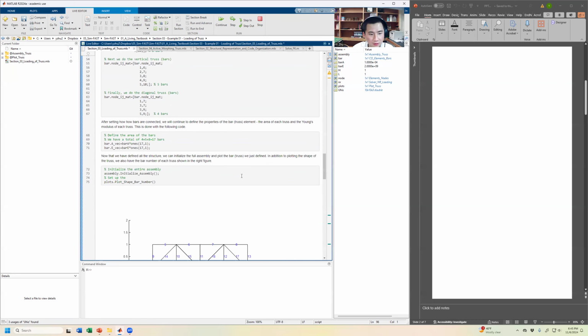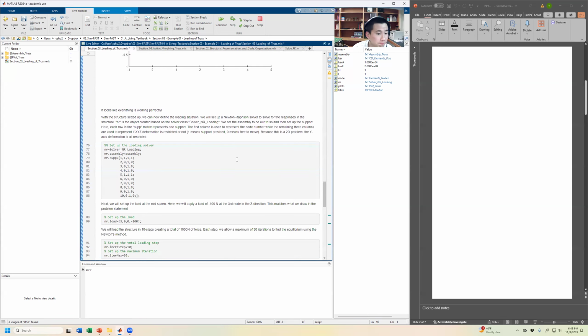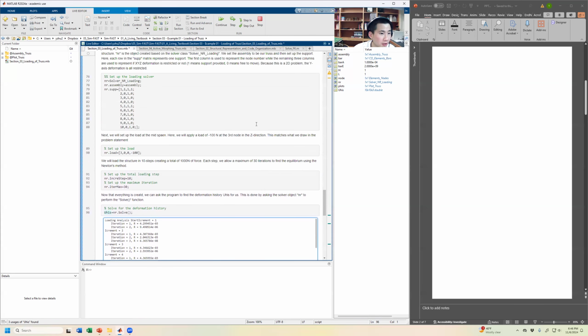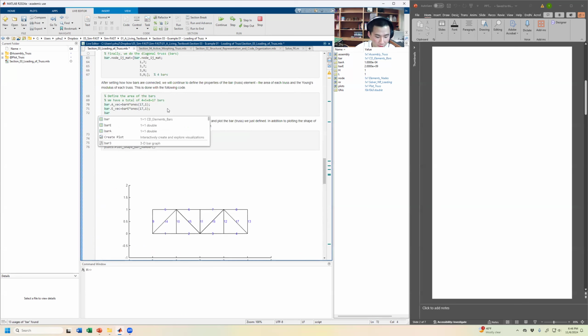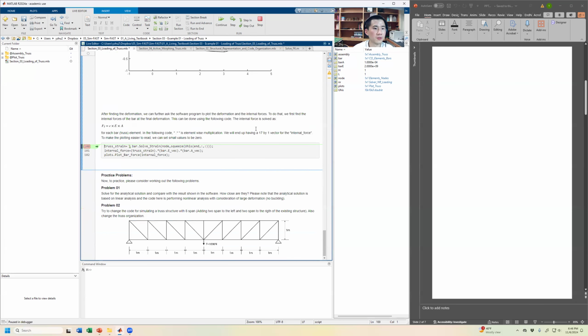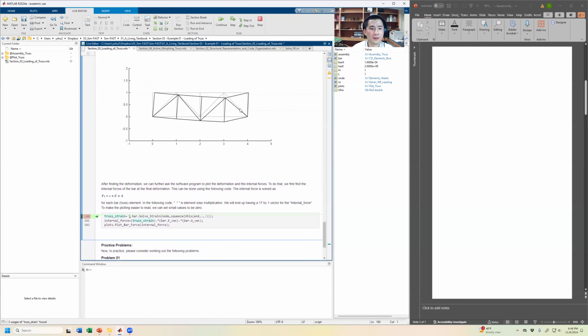And let's see what's the number of that bar. Okay, 17. All right. So what we can do to make that bar soft is E vector 17th. Make it 100 times softer than what it used to be. Let's do that. Divided by 100. So that will make that bar really soft. And let's hope that our algorithm can converge. Oh yeah, it did. So there we are.